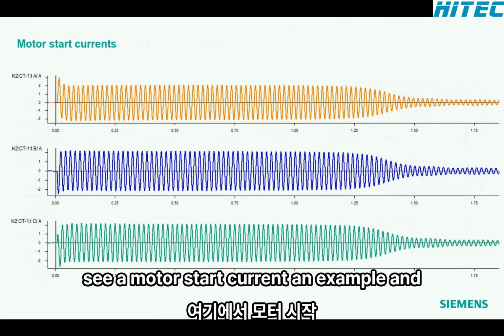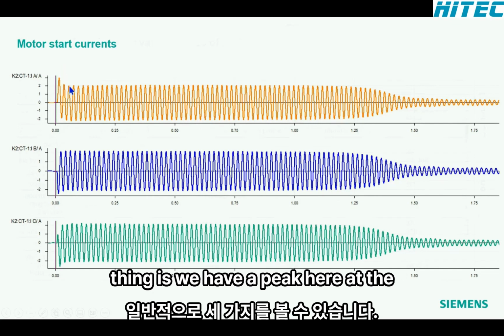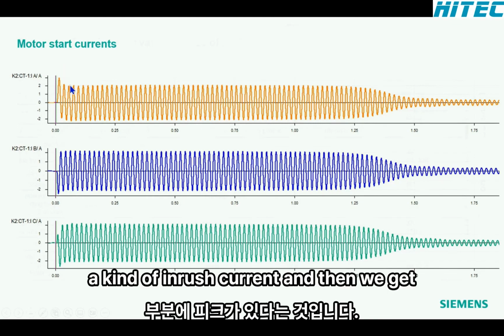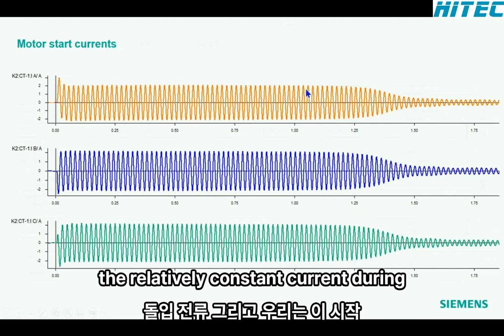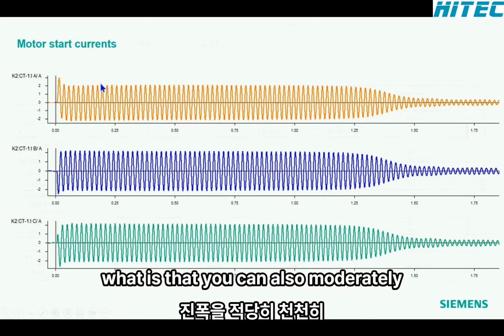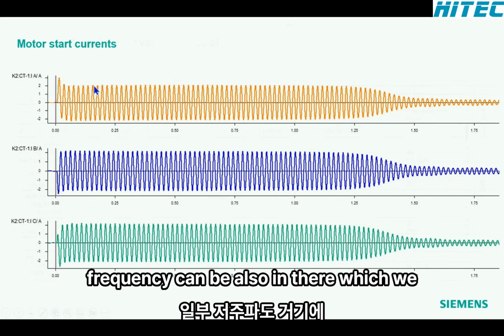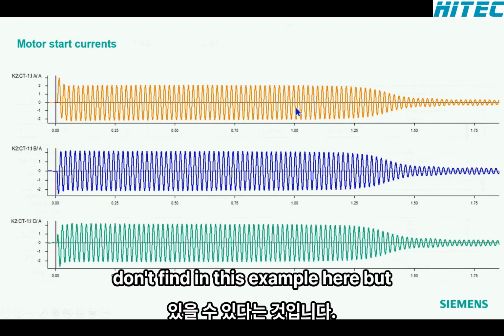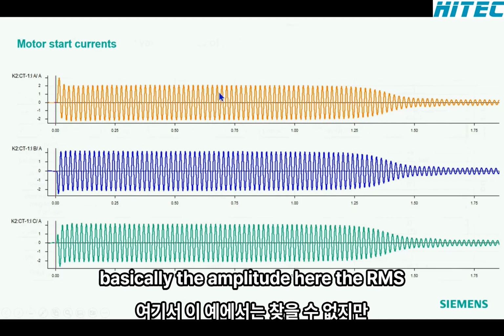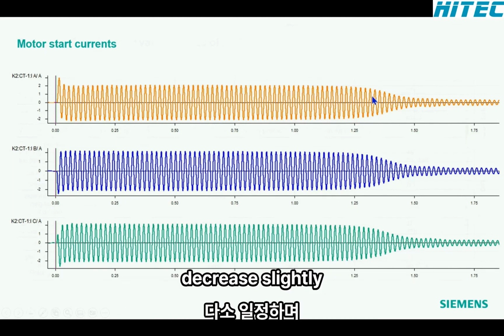So here we see a motor start current, an example, and we typically see three things. The first thing is we have a peak here at the beginning, a kind of inrush current, and then we get a relatively constant current during the startup phase. This can also change its amplitude moderately slowly. Some low frequency can also be in there, which we don't find in this example here. But basically the amplitude, the RMS value, is more or less constant. It can also decrease slightly.